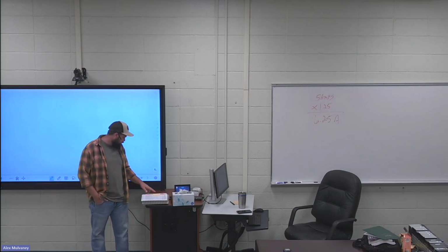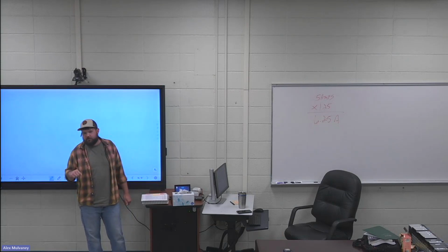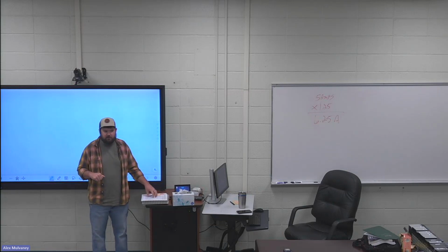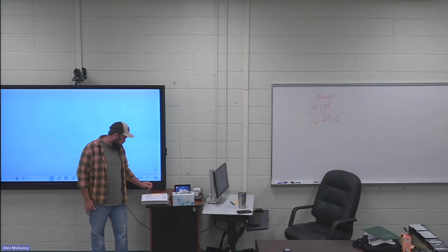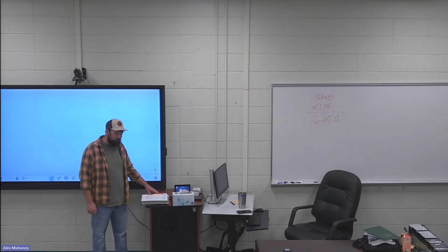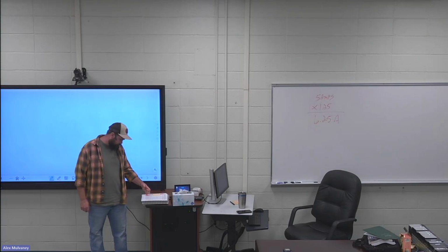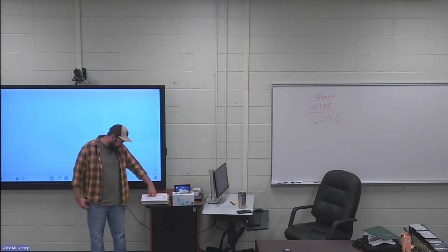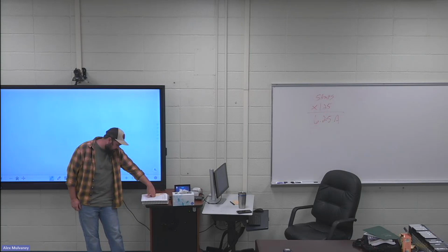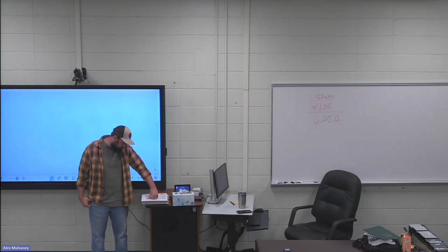Solution, Table 220.55 Note 4. This is one of the more difficult things to do in this chapter. So please follow along in your NEC book while I'm going through this, because I use the notes at the bottom. All right. So 220.55 Note 4. So looking in here, you look to the bottom of Note 4, branch circuit load. It says, it shall be permissible to calculate the branch circuit load for one range in accordance with 220.55.